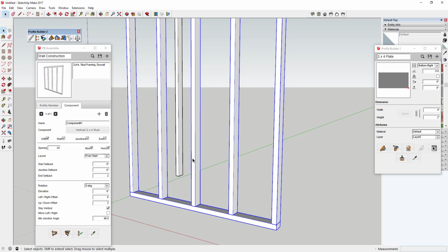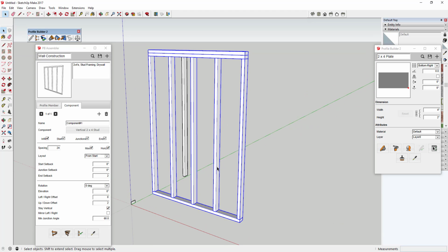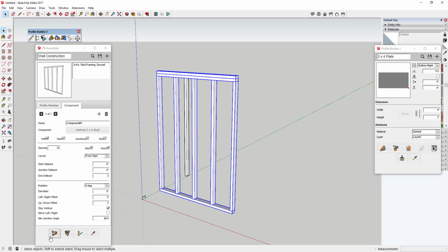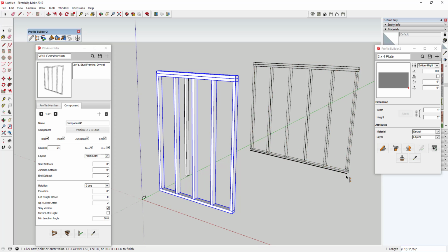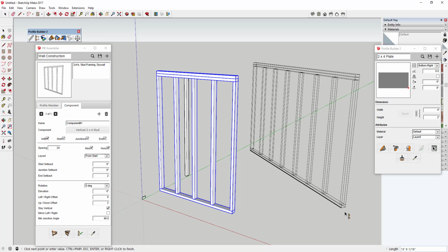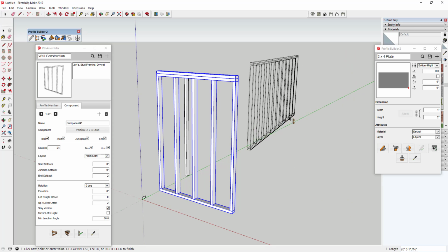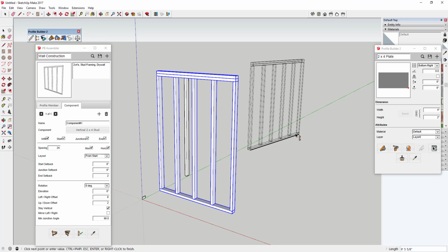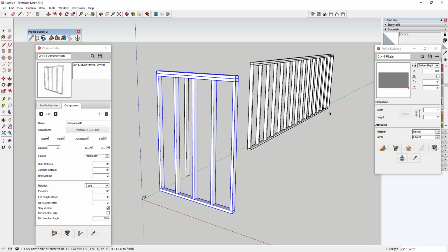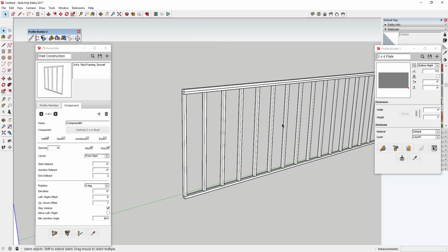And you can see how it adjusted the spacing when we did that. So now you've got this 2x4 stud wall object that you can click and add in here. If you just wanted to stop here, you could click this build assembly option and then click a couple times, and you can see how it's building this wall and spacing all your objects at 24 inches just like this. As you extend your wall, it's adding studs in there. As you take your wall back, it's bringing them back. So now you've got your stud framed wall in here.